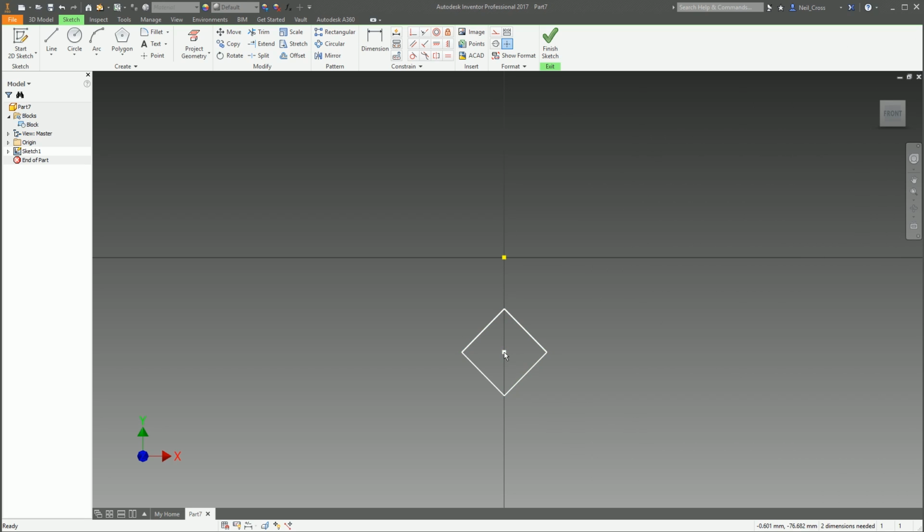But this block is now placed, and it's sort of free to rotate around like that, but you can see the edge is constrained to that center line, which is fine. So we can just put a vertical constraint between there and then there. Right click and OK, and then this will now move up and down that edge.